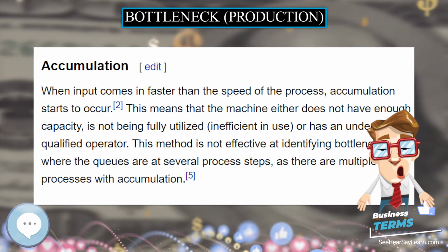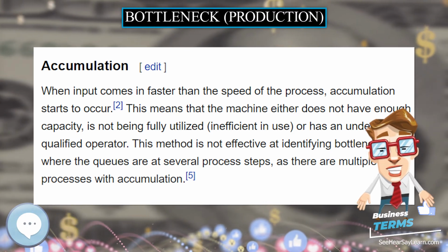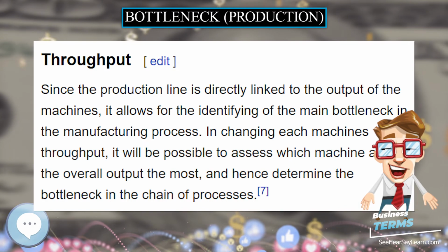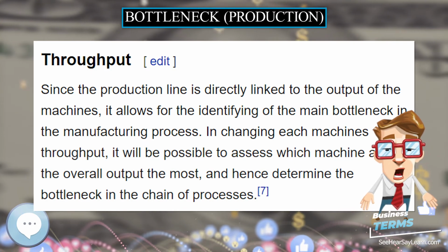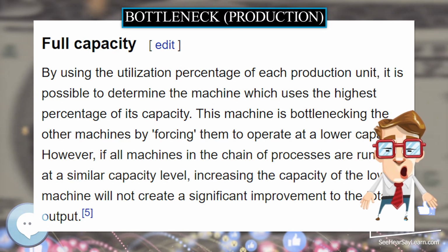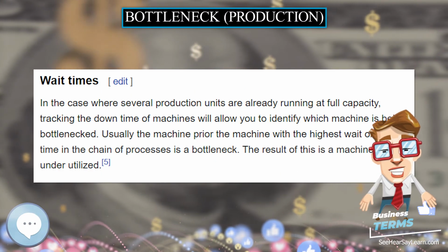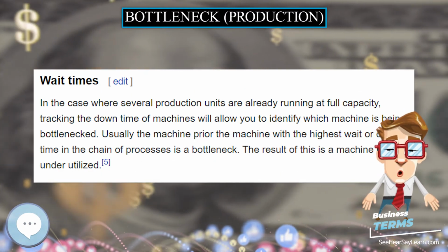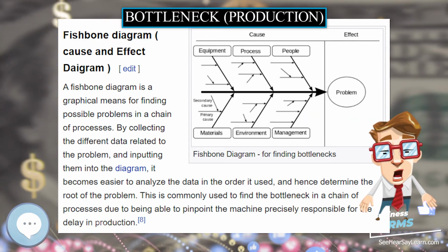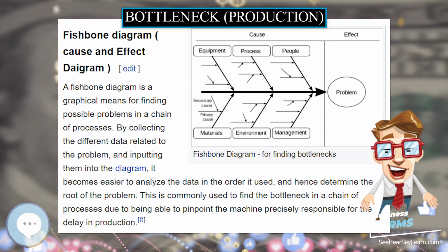A static bottleneck is where no random or unexpected fluctuations, such as those that would happen during either a changeover or a breakdown of the system, occur. A static system does not change in behavior and hence the system stays constant. Finding a bottleneck in a static system is very simple. It is simply the machine or process with the longest constant cycle time.